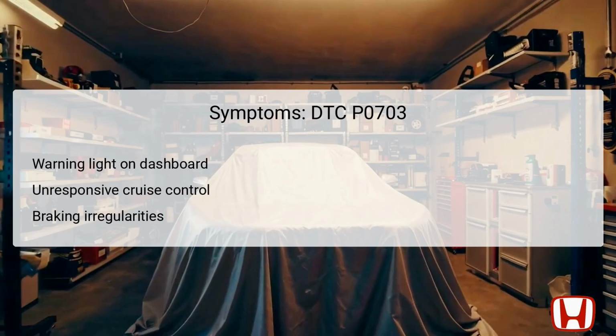When experiencing DTC P0703, several symptoms may manifest. One of the primary indicators is a warning light illuminated on the dashboard, specifically signaling an issue within the braking system. Drivers may also notice irregularities in the cruise control functionality. This may include it being unresponsive or disengaging unexpectedly.